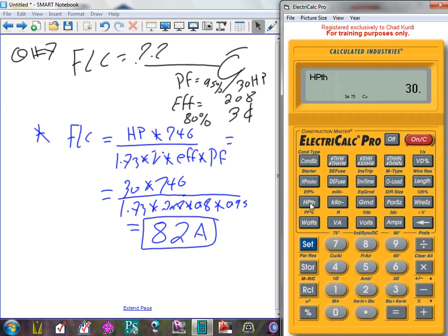The next thing you need to set is the efficiency. What's my efficiency? 80. Here's your efficiency, 80. Your power factor is 95. And where's my power factor? My power factor is set with watt. That will give you the power factor. Anything else I need to put? 3-phase. The calculator is already set for 3-phase. I put the efficiency in by set. And if you hit the amp, you end up with, is that what you came up with, guys? Yes. That's cool, isn't that cool? So I could have discovered my mistake so easily, it was 480.